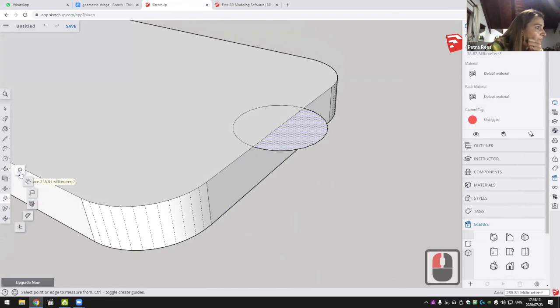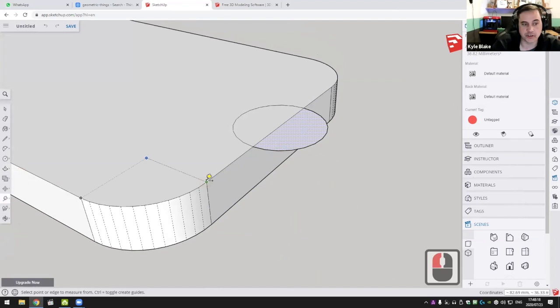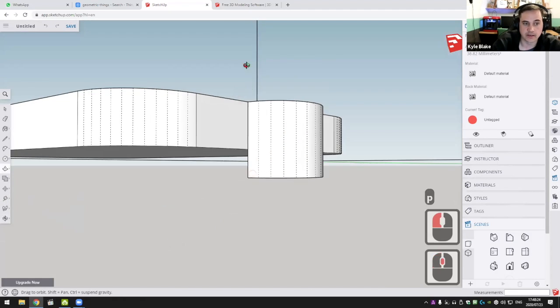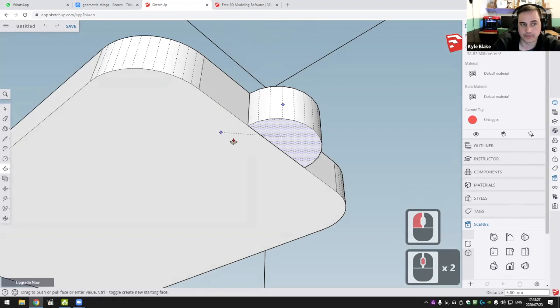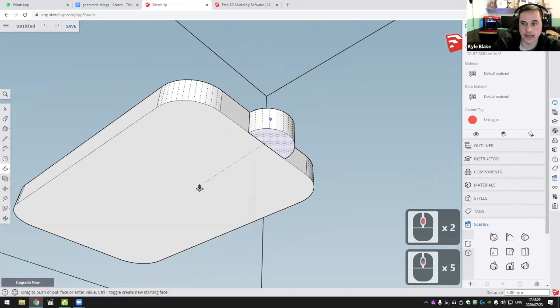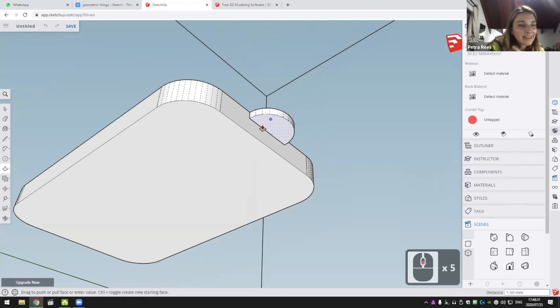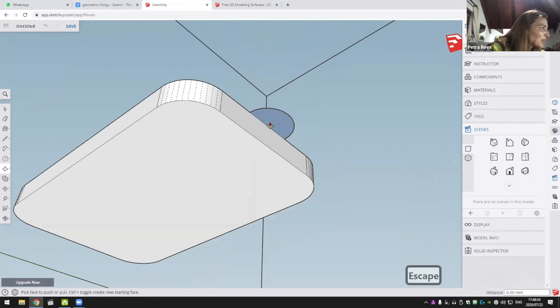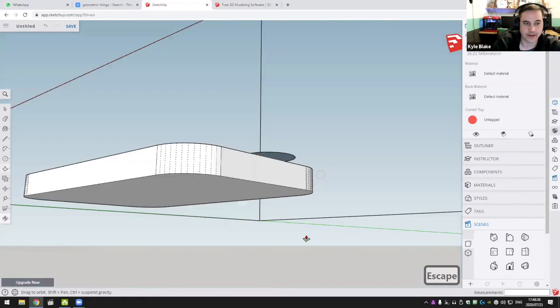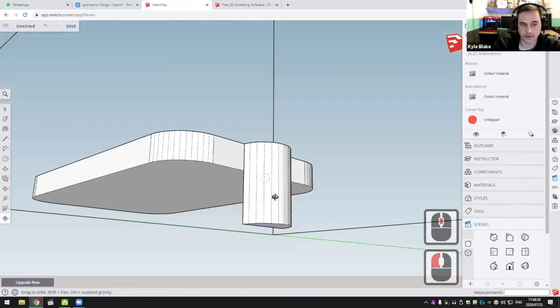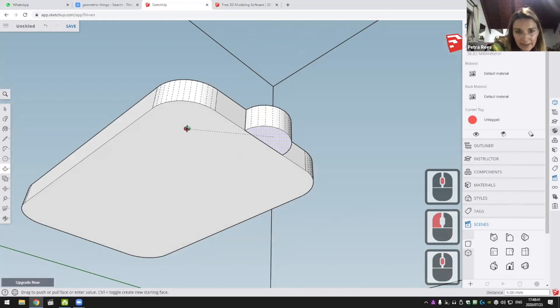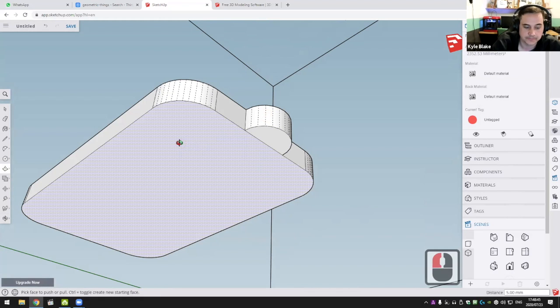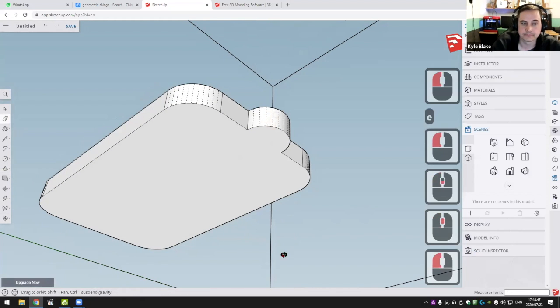Okay. Which is the first tool here. And then you can measure top to bottom how tall you've made it. So I know I've made it 5. Or if you just use the push-pull tool, in the first click, the second click, you can actually just tell it to snap and end on this face. So it will align it automatically for you there. Where does it, sorry, that one? Just do it again. The push-pull tool. Yes. So if I click on it and I pull it, so you're saying right now it's pulling past. Yes. You can just click on the face where you want it to stop and it will automatically line up. Yeah. Okay, thank you.